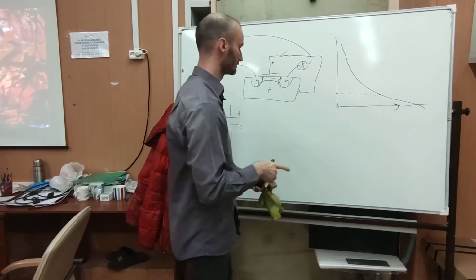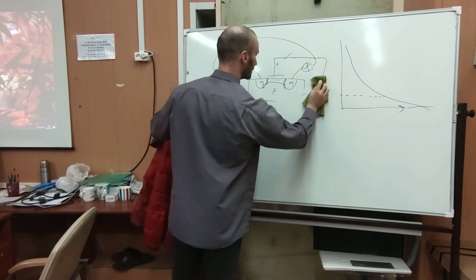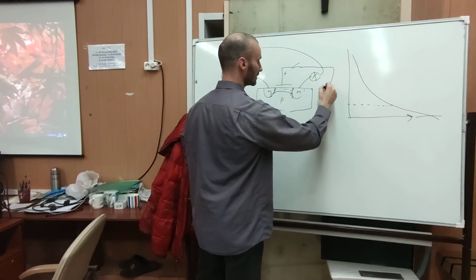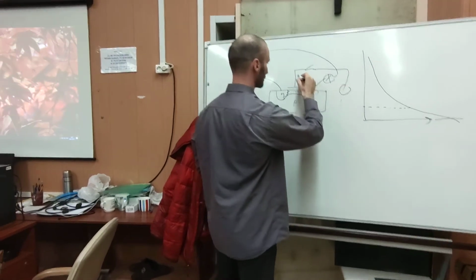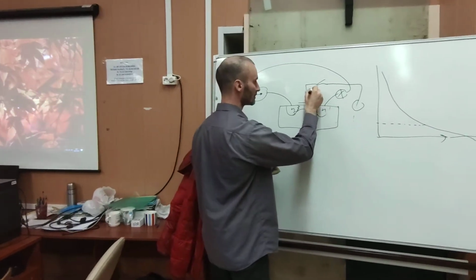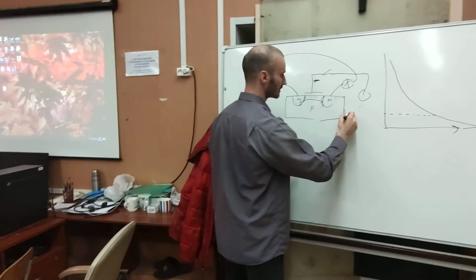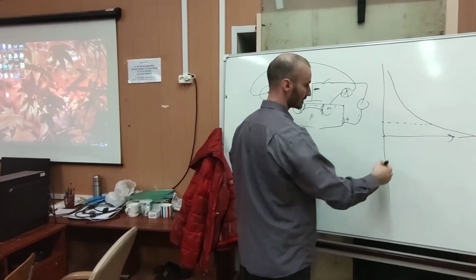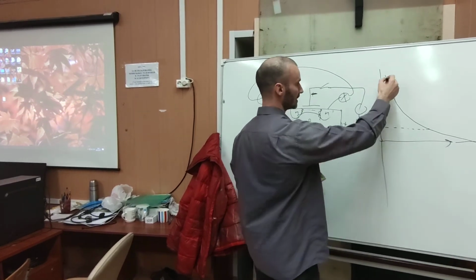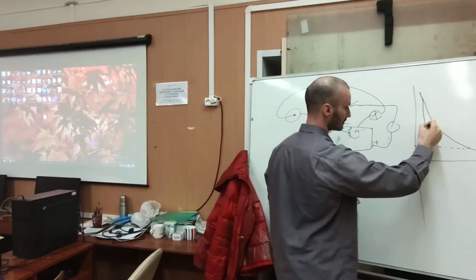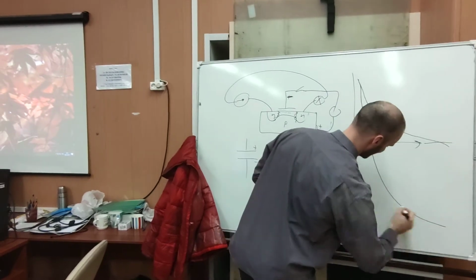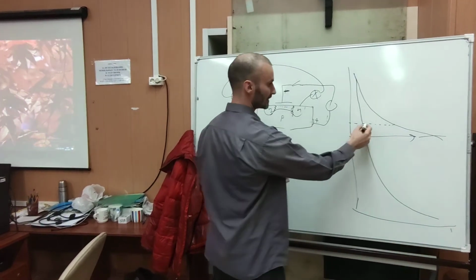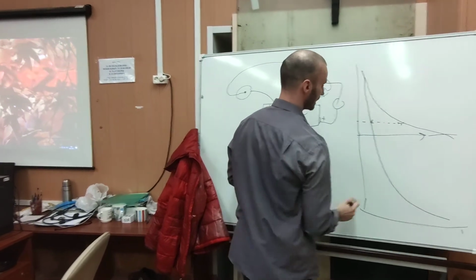We want it faster. To make it faster, we will not just connect them. We will apply voltage in the opposite direction. So we will make this voltage negative and this voltage positive. So what will happen is, the same graph with time: the charge will drop like this, and that will be negative. Much faster. You see the difference.